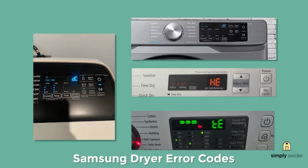Now you're equipped to handle the most common Samsung dryer error codes. Here's your action plan. First, prevent future problems by cleaning your lint filter after every single load and checking your outside exhaust vent monthly. This alone prevents 80% of error codes. When errors do appear, start with the diagnostic button sequence we showed you, then work through the troubleshooting steps for your specific code.